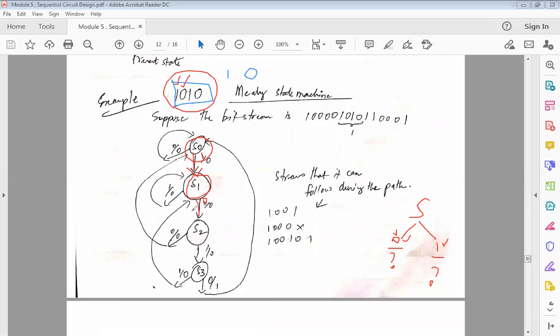Next it will move to another state from S1 to S2, and that will happen when we have got 0. Now from S2 it will move to S3 if it has the value 1. Which means this third bit is also done. Now in our last state S3, it will complete the loop and go back to the initial state if and only if it receives 0. So this part is also done.